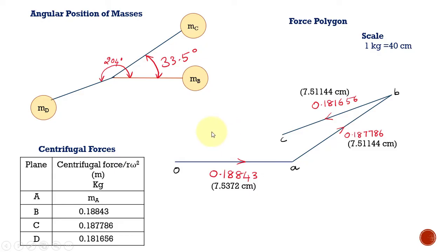Okay, so now you can just think of that. The force polygon is not closed, but we have another value which remains unknown, that is the MA value. So the closing side is exactly equal to this value MA. Okay, so this is the closing side, and the direction must also be taken in the same order.